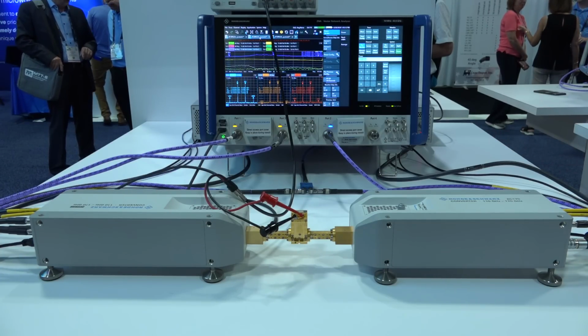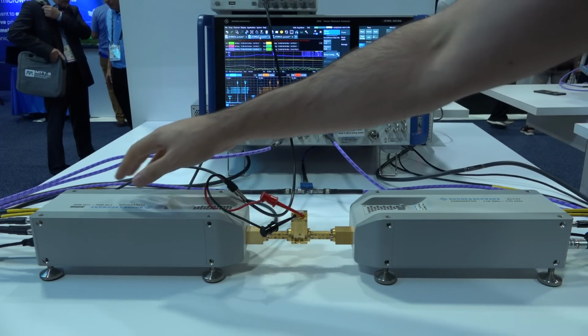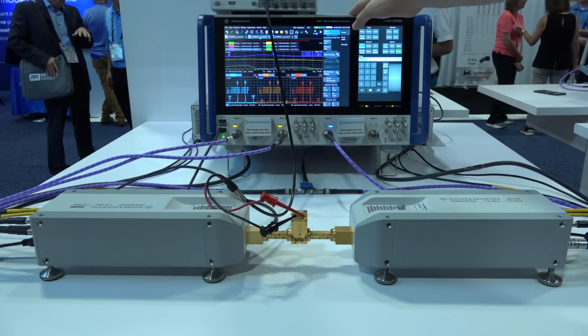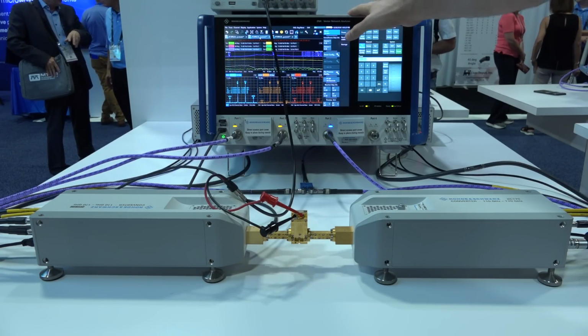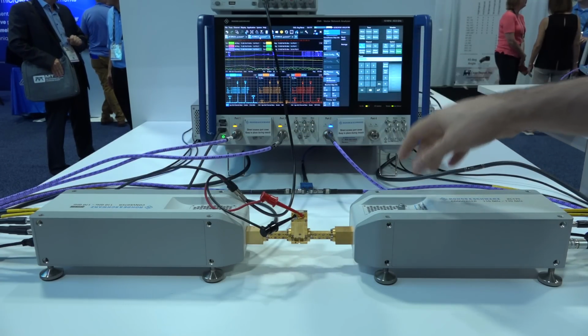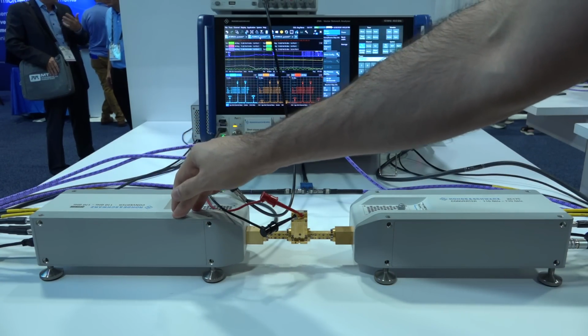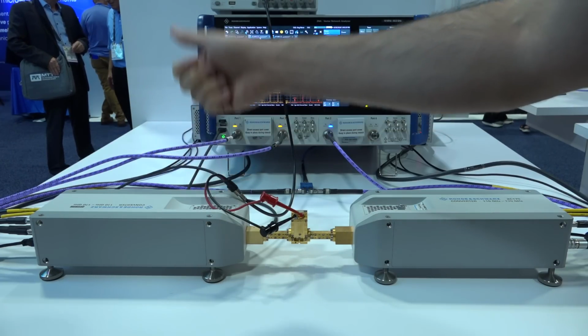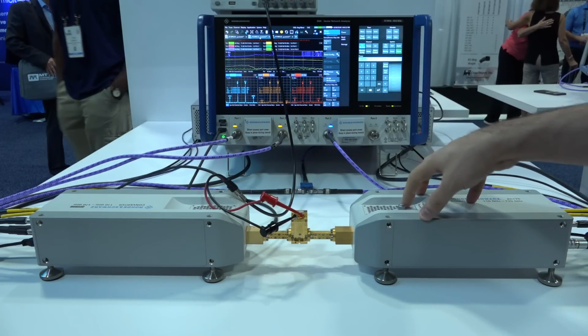And here we have the ZNA, this time connected with the frequency extenders between 110 to 170. Of course, the ZNA, you should now know, is the ultra-high dynamic range network analyzer base, which can be connected to all these extenders. Now, 110 to 170 gigahertz extenders in this case are actually two-tone generators, so there are 2 up converters and down converters in each one, so that of course gives you OIP3 measurement, IM3 measurement directly from the units themselves.